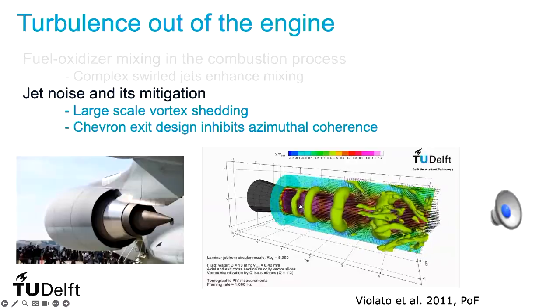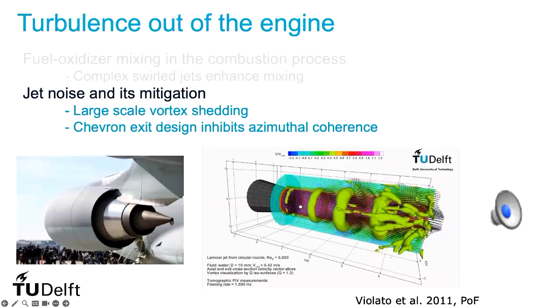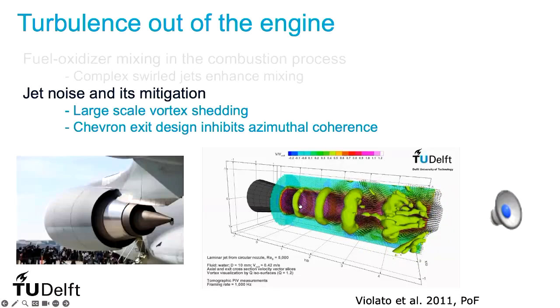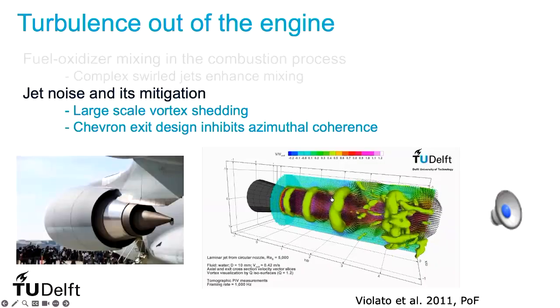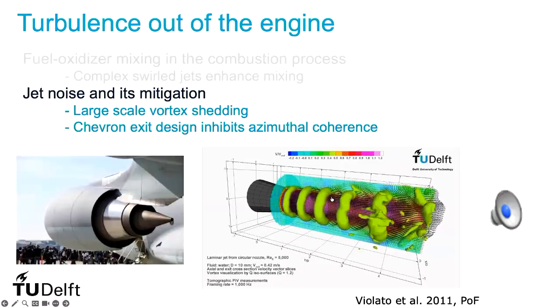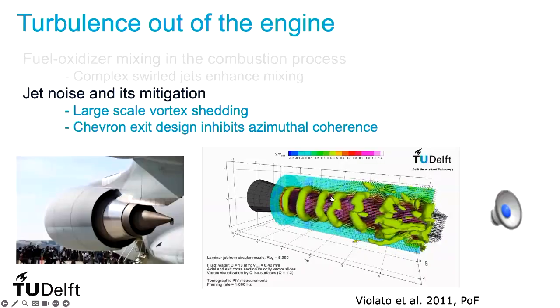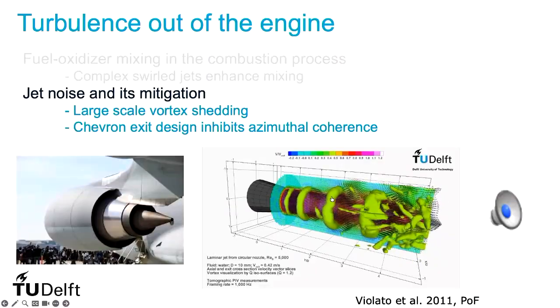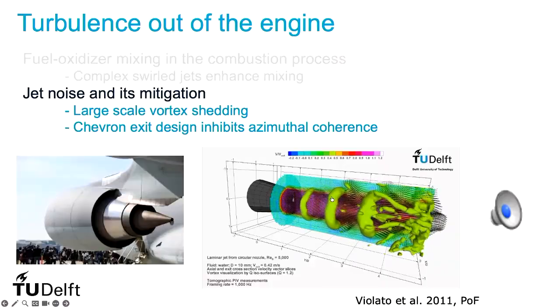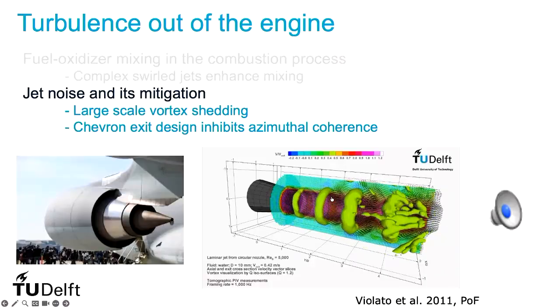And here, again, we can see the Kelvin-Helmholtz vortices. Some of them are disappearing, and maybe it would be nice to look with the vortex detection system that they don't really disappear, but in fact, they decrease their intensity because they are trapped into the leading vortex. And you can see that right after this leapfrogging, it's called leapfrogging mechanism, and after leapfrogging, then the azimuthal instabilities explode, leading to more and more isotropic type of fluctuations.